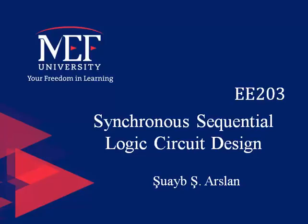If you remember from our previous class, the analysis of sequential circuits commences from a given circuit diagram and culminates in state equations, state table, and finally a state diagram. The design of sequential circuits starts with a set of specifications. This was also the primary step in combinational circuit design. Then the procedure continues with drawing the corresponding logic diagram.